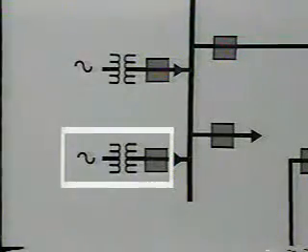Any fault within this zone would result in tripping of the main generator breaker here, and hence isolation from the power system. This will protect against faults in 1, the generator itself, 2, the primary of the transformer, 3, the secondary of the transformer, and 4, the breaker.